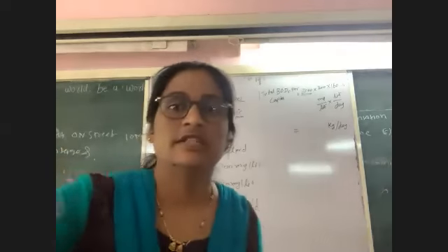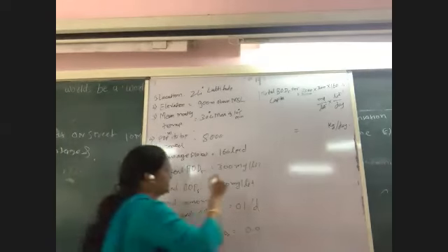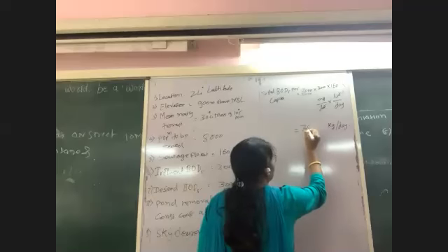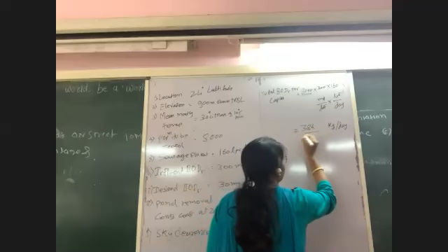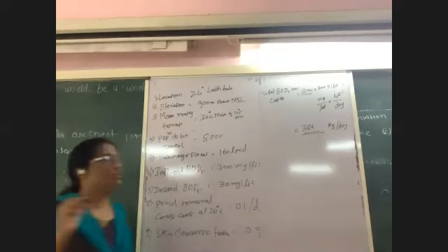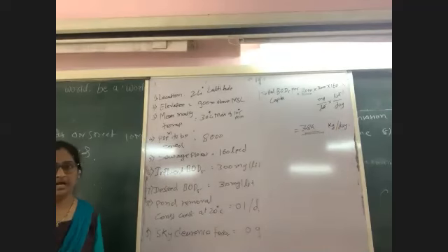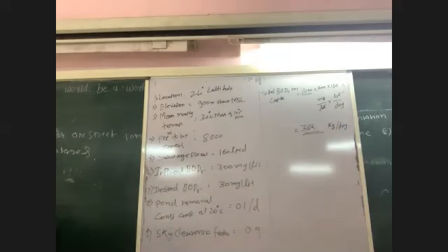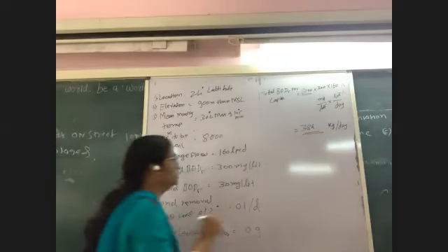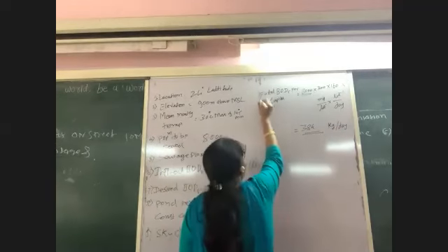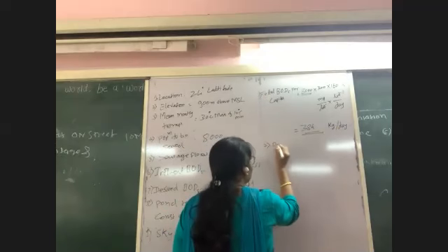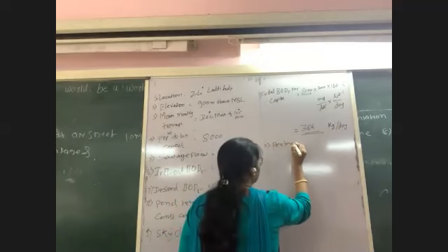Yes, 384 kg per day. Correct. 384 kg per day is the answer for total BOD per capita. Now for that BOD, we can go on to design the oxidation pond. So the next step, we should go for permissible aerial BOD loading. This is the first step. Second step, you should go for permissible